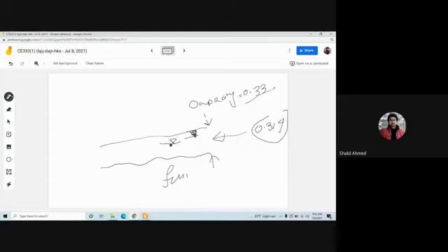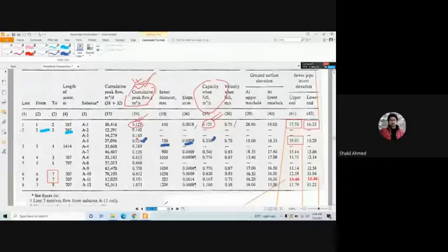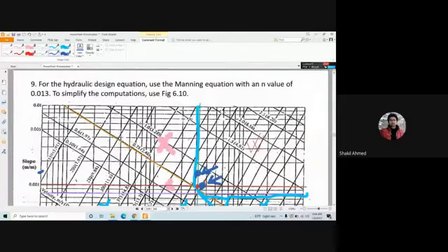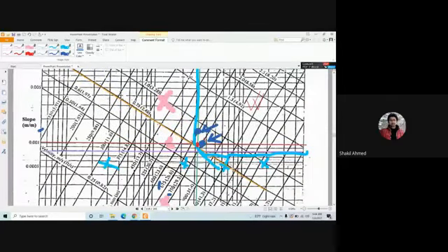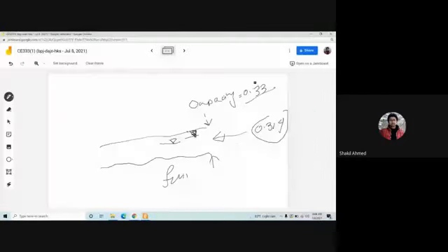Now, due to this partial flow condition, the velocity that you are getting at this point is what, guys? The velocity for this point is around 0.75 here, right? Yes, sir. Maybe 0.78. Right? 0.78, sir. Yeah, 0.78. But the question is, 0.7 is for what condition? The 0.7 is for this condition when the flow will be at the top. Then the flow will be what?